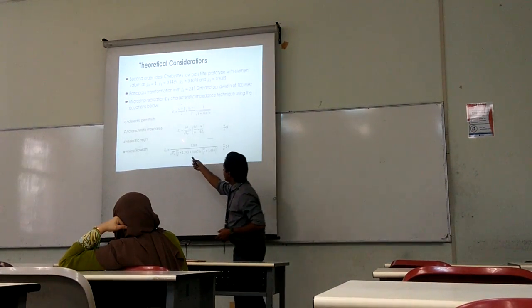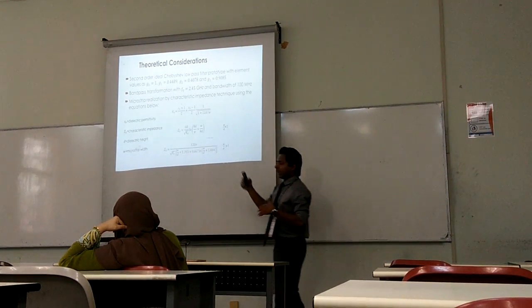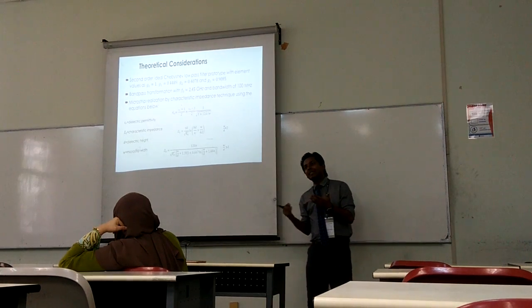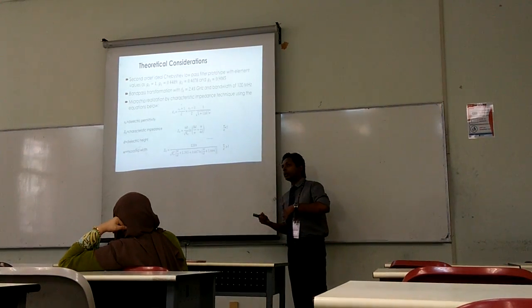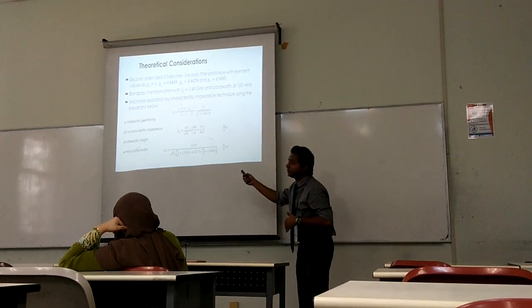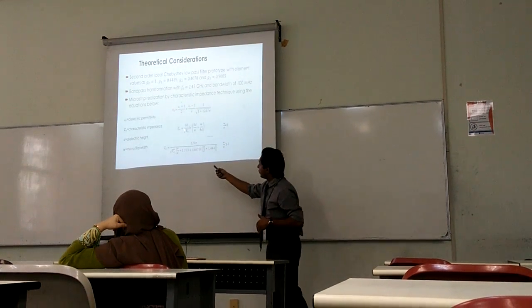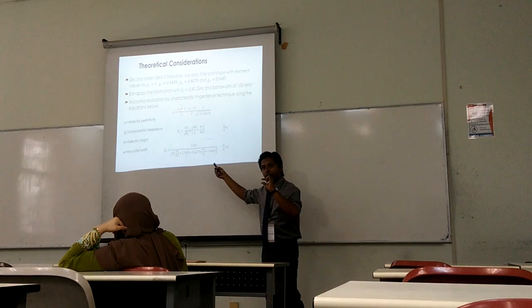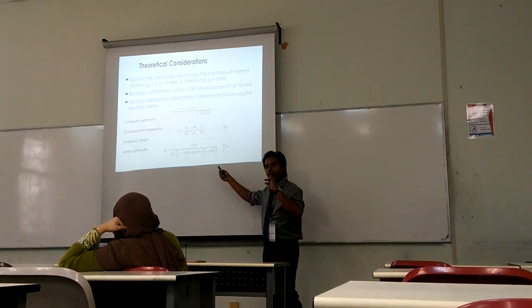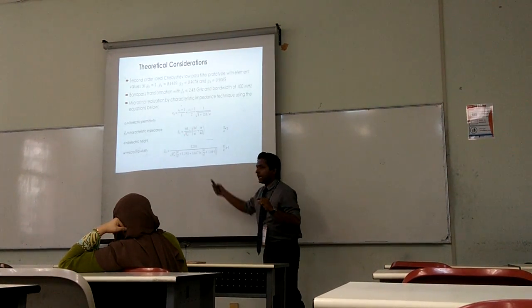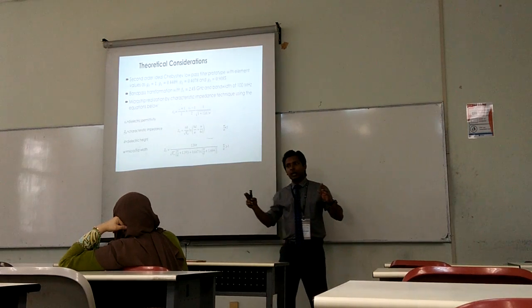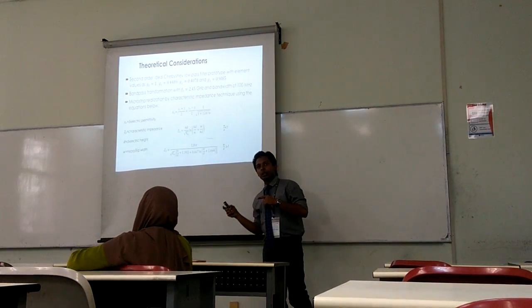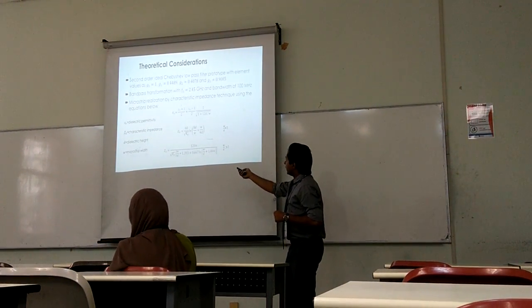But the one thing I have to mention here, we have used the characteristic impedance technique to translate our theoretical design into microstrip level. So we use this equation where this W is very important, the width of the microstrip line that determines the characteristic impedance, and we all know that the length of the microstrip line is related to the electrical length of the microstrip line.